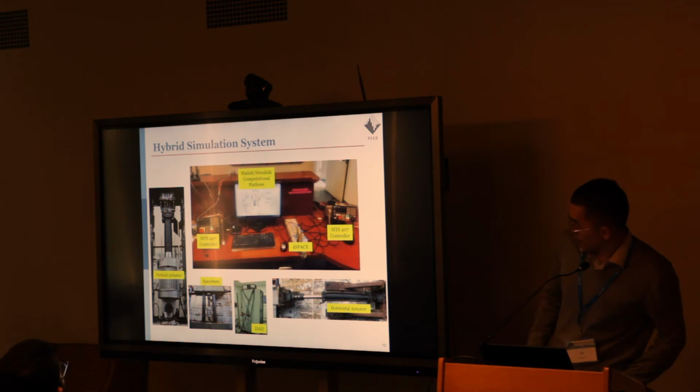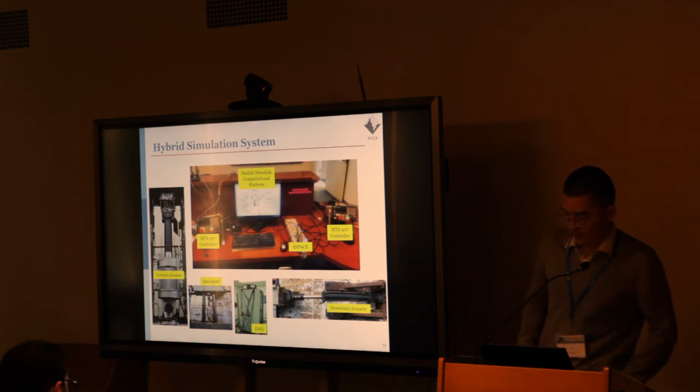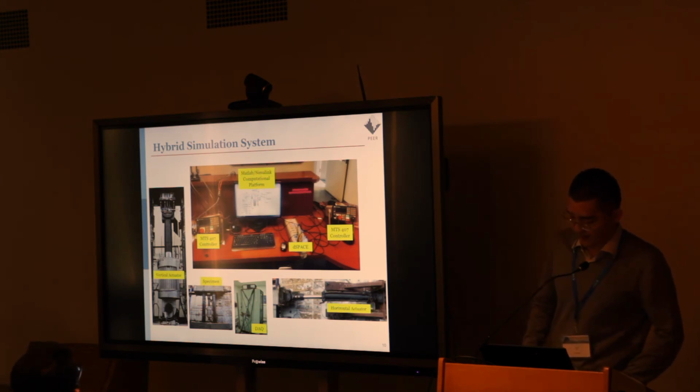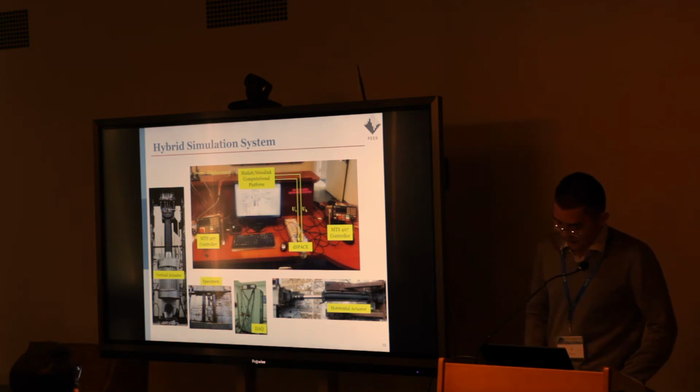Here is the newly developed hybrid simulation system and its components. Here, two uncoupled single degree of freedom equations were numerically solved using the MATLAB Simulink computational platform. And after the displacement has been solved, the computed displacements need to undergo interpolation, and then they were sent to the controller after the digital to analog conversion.